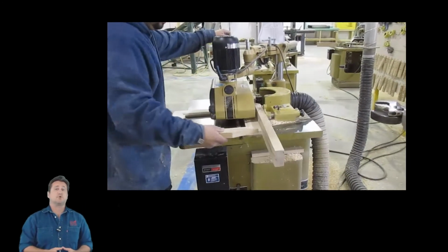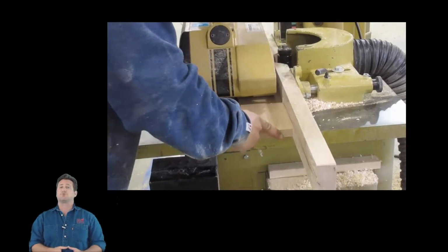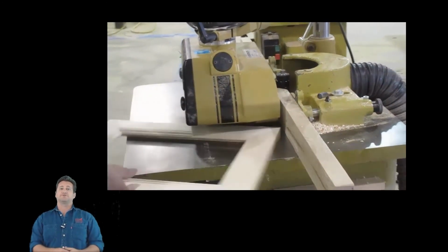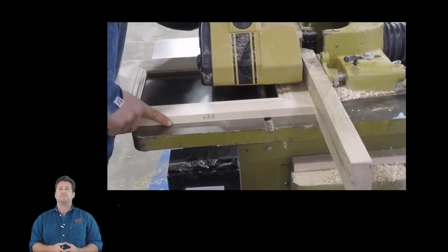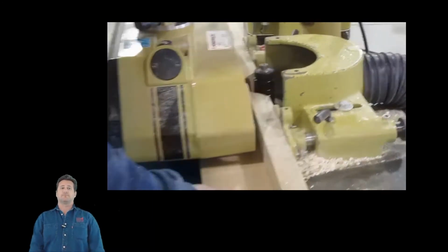Next, the door moves to one of our edging machines. There, the shaker door receives its traditional square edge. This edging process removes 1/16 of an inch from each stile and rail, bringing the door down to its final width and height dimension. The edging process for a shaker door is being shown.